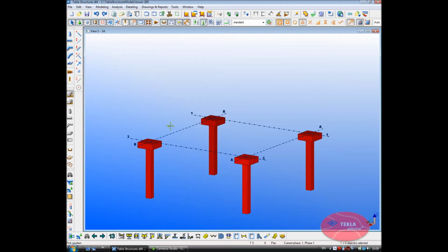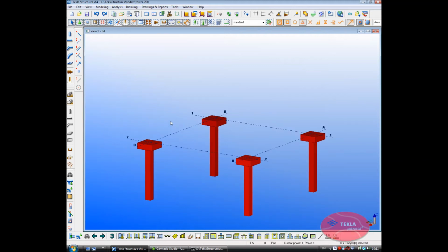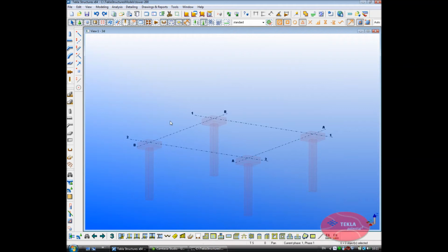The next thing we're going to do to that is add some rebar, some reinforcing. So first thing we'll do to help me do this is change the transparency level of the system. So I'm going to set this down to what we call Control 5, Shift 5, which is a sort of transparency option. If we click on the pieces, you can see each piece then, as we window certain areas, as solid.